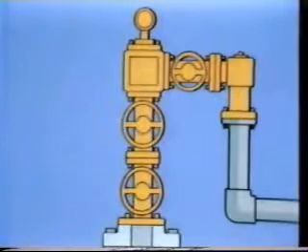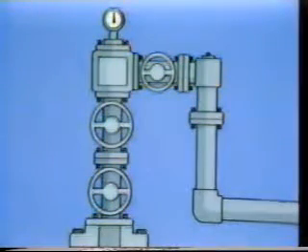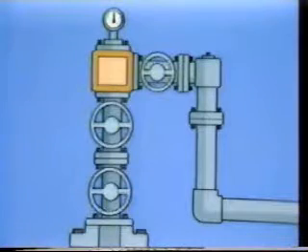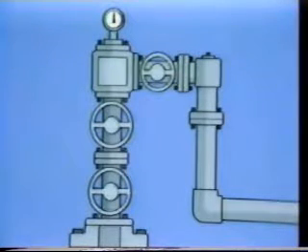The equipment above the tubing head is referred to as the Christmas tree. The bottom valve, often called the master valve, is the primary means for completely shutting in the well. A T-type fitting allows for redirection of the vertical flow stream to a horizontal flow line. For a flowing well, the produced fluids, before entering the surface flow line, must pass through the smallest restriction in the surface flow equipment, the choke.